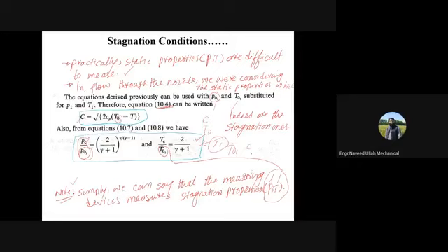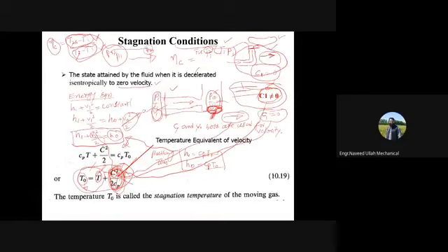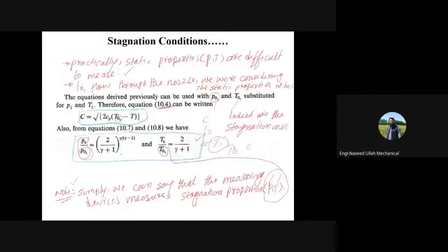That is, if you know T01 and you know the initial velocity also, can you find out this T? Yes, because Cp is known, 2 is constant, and if you know C and T naught, you can find out T. You can readily use those formulas. But this is an extra calculation, so that is why we directly use the other one. Did you understand? What I mean is, if you take, let's say, TC by T1 and you know T01, then either use the direct formula, or, which is not the practical case, if you want to solve using that formula, you can do that.